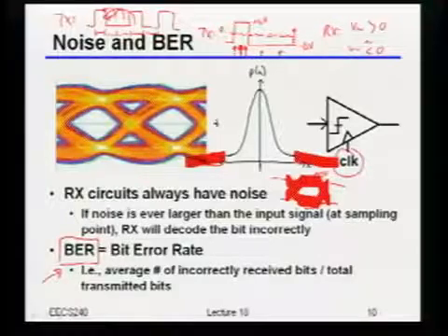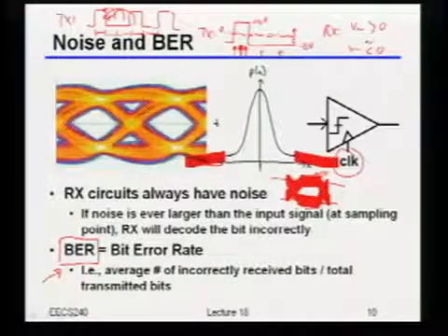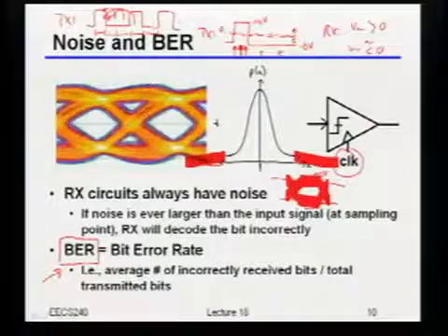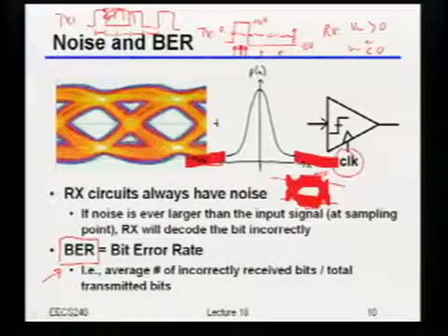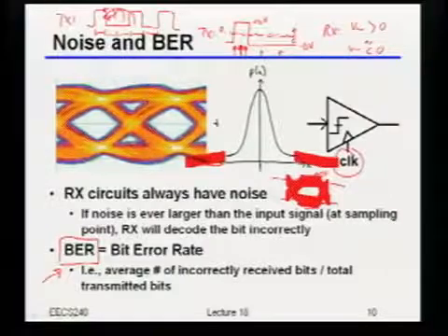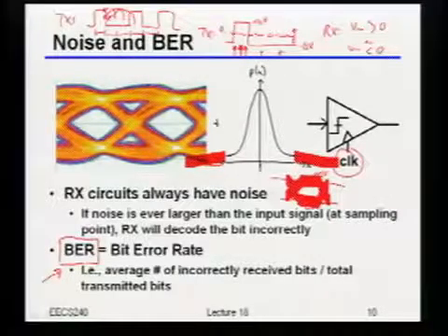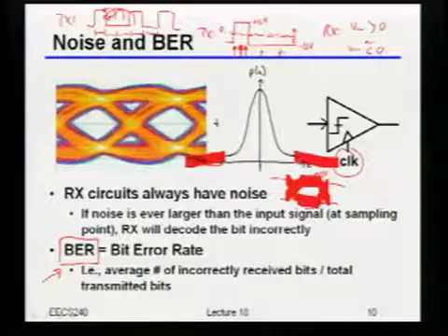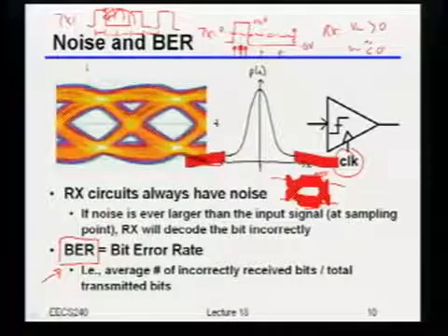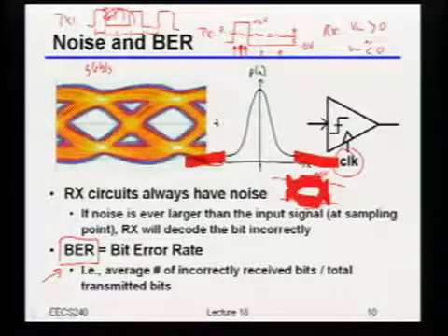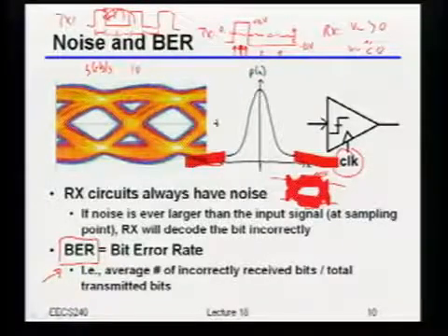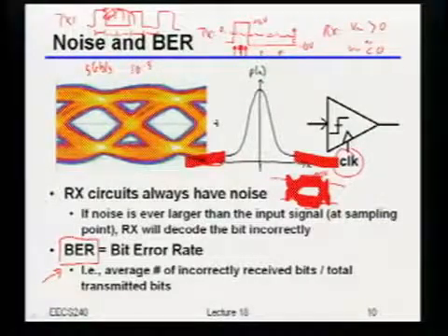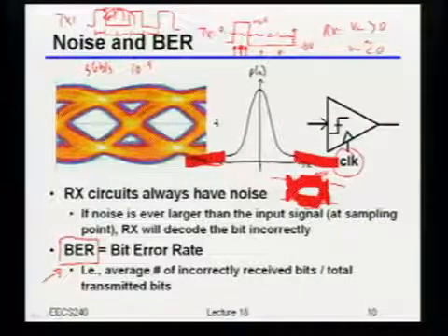what sets how much you care about this bit error rate is how often you can tolerate making errors. Well, I don't know about you guys, but at least for me, if it's my laptop, I want to make sure that it basically never makes errors, probably over the lifetime of how long I'm going to run the thing. So now, if I'm running at 5 gigabits per second, and I had a bit error rate of 10 to the minus 5, on average, how often would I be making mistakes?